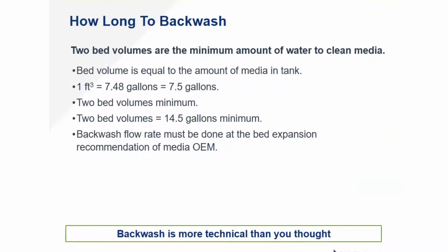This is a good approximation, because a little excessive backwash is not a bad thing here. So 1 cubic foot is about 7.48 gallons, 7.5 gallons. 2 bed volumes minimum is going to be about 14 to 15 gallons of water minimum required.